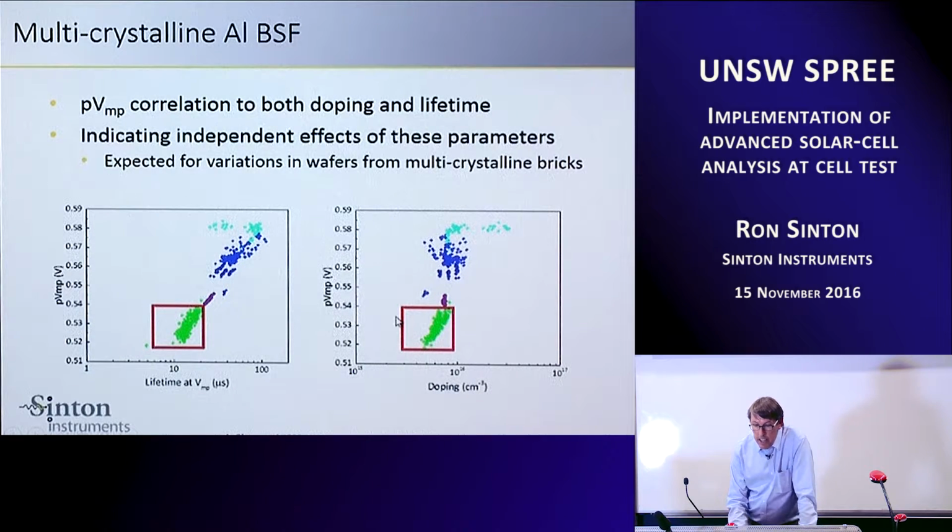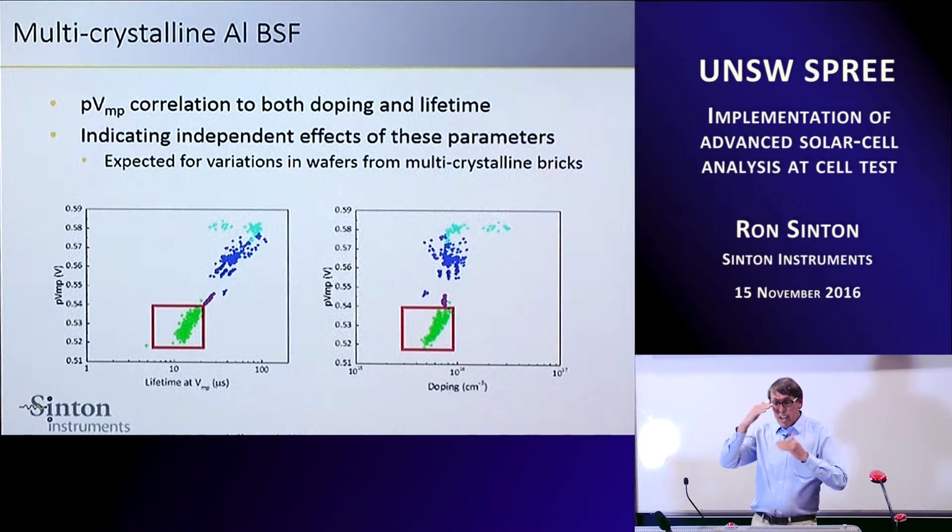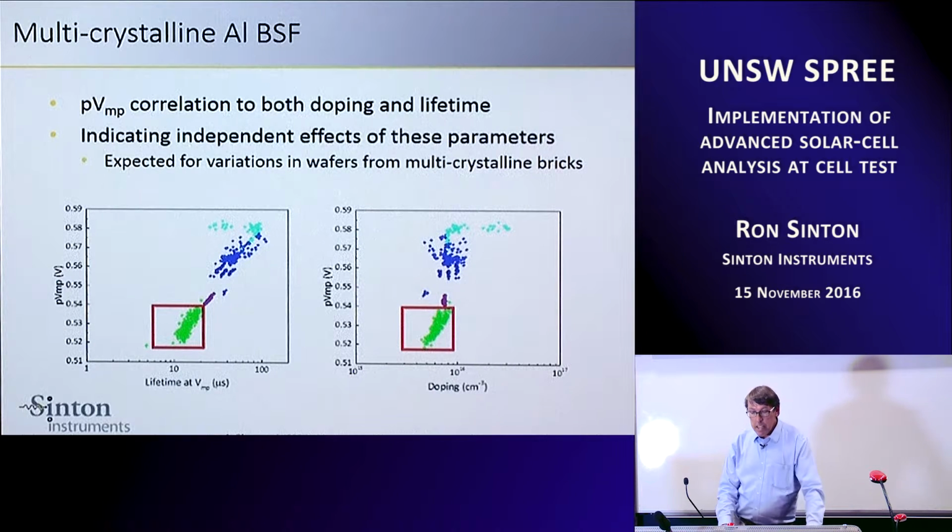Then if you look at the aluminum BSF, we're using the entire ingot here, and being a conventional ingot, you get a wide variety of lifetimes due to different defects at different points in the crystal, as well as doping. So there's both a lifetime and a doping dependence.